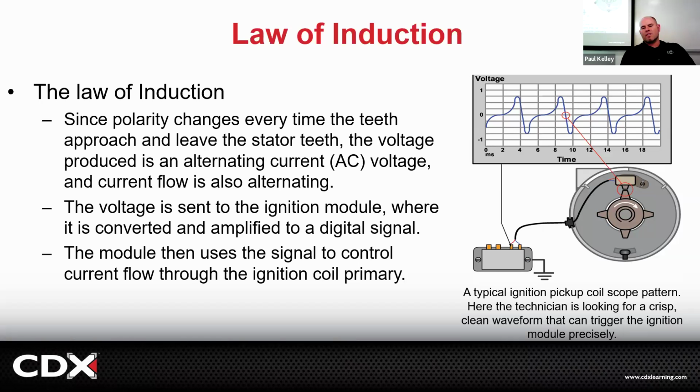If we go into the first type of distributors, those don't even have a pickup. They don't have any of this induction. They actually use breaker points, which make a connection and break a connection. But the problem is they make and break over and over until they fail. So we get away from that and go more into this induction. This really shouldn't fail because those are never actually touching. This tooth just goes by that sensor, and when it does, it induces a major voltage.